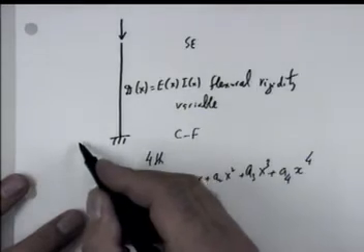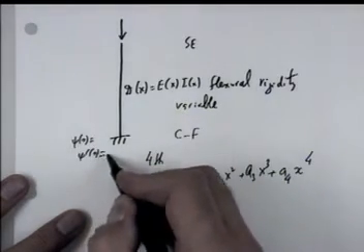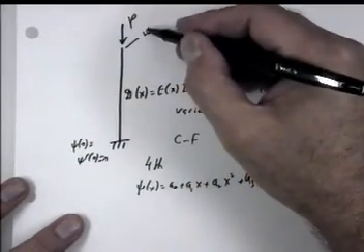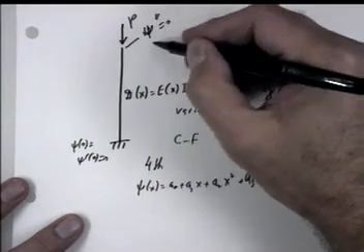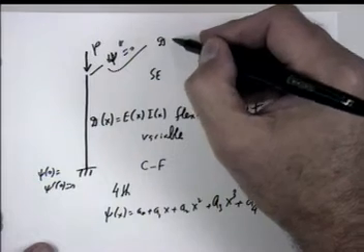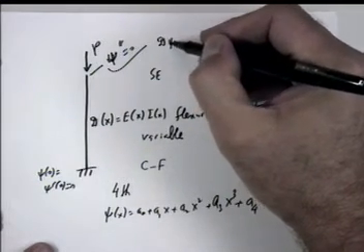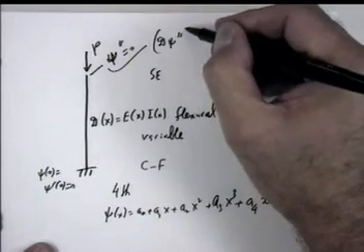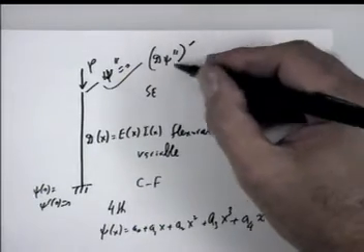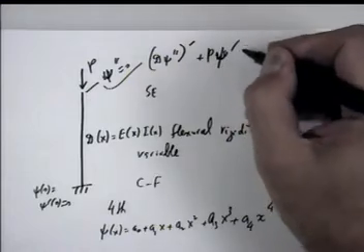Then you satisfy boundary conditions: psi at 0 equals psi prime at 0 equals 0. And boundary conditions here will be psi double prime equals 0, and then D times psi double prime, that is a moment, times first derivative, that is a shearing force, plus P psi prime equals 0.